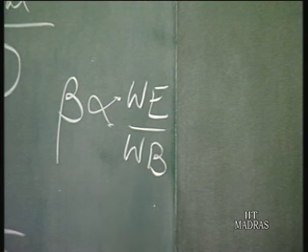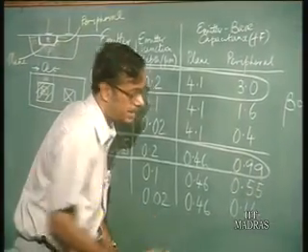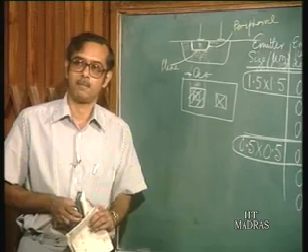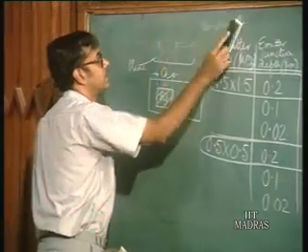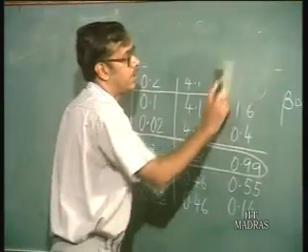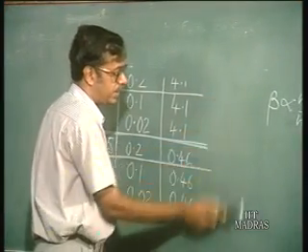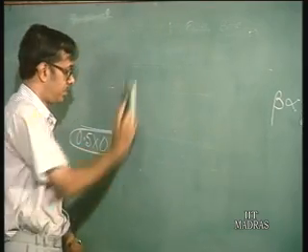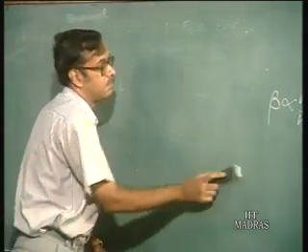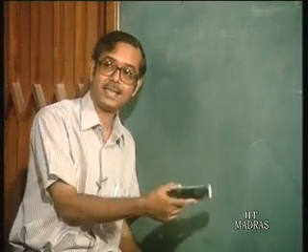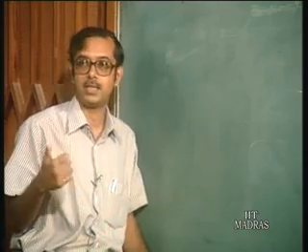So, what is the solution? Well, the solution came in the form of a particular type of bipolar transistor, which is called the polyemitter bipolar transistor. I am just going to discuss that. What is a polyemitter bipolar transistor? In a polyemitter bipolar transistor, the advantage is that you can reduce the emitter junction depth without affecting the beta of the transistor. That is the major advantage.